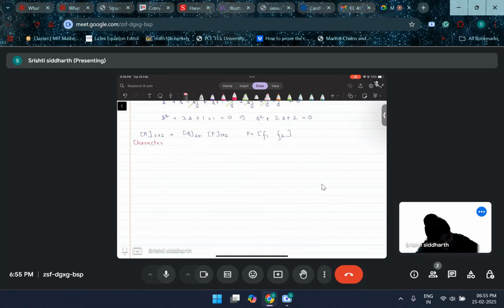The characteristic equation of the closed loop system A plus BF. This can also be A minus BK, the form which we have studied in the lecture slides, but this is also fine. Or you can also find A minus BK, with F equals minus K.